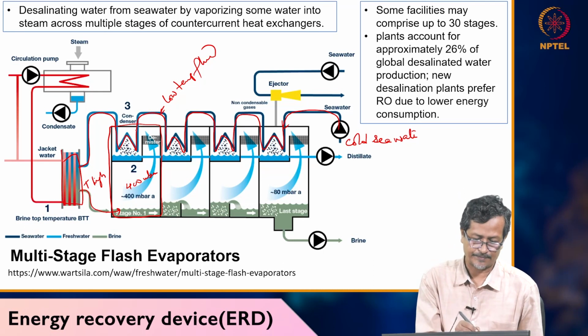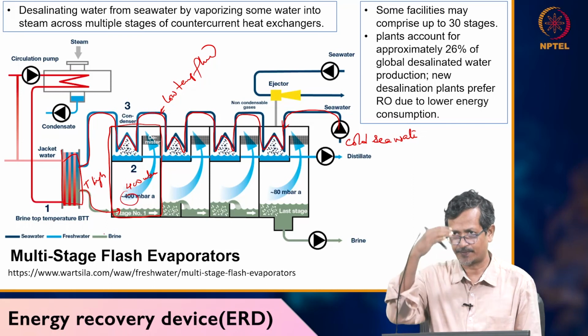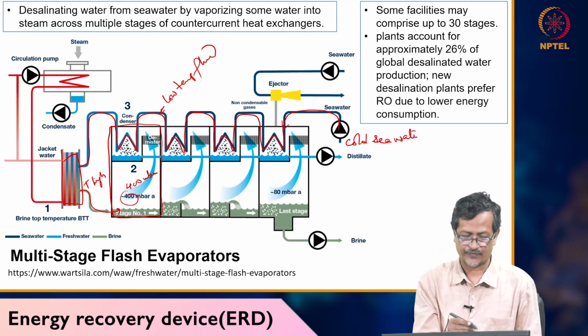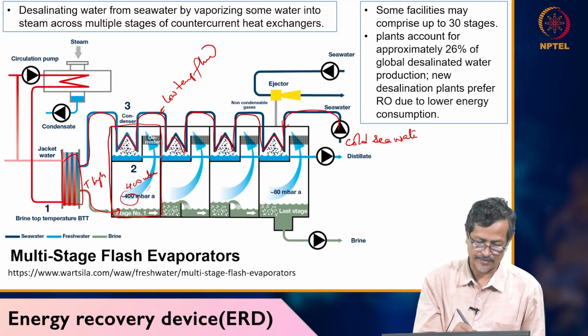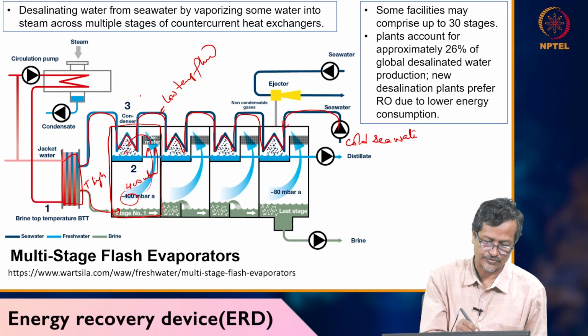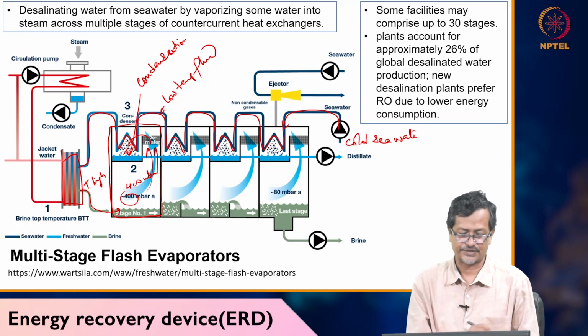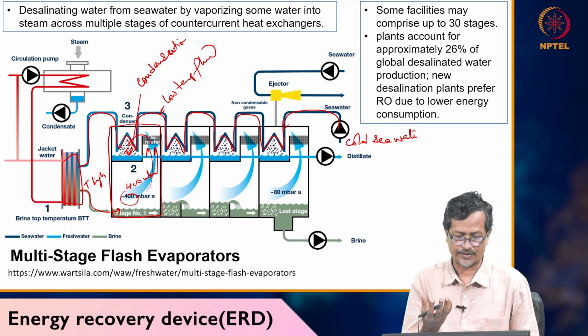Okay. Some fluid is coming to the first chamber after heating. Now, here pressure is lower, 400 millibar, and in the upper part some cooling pipe is also there. When it gives off lots of vapor, the vapor will get cooled down and collected here. Okay. So, here vapor is cooled, condensation. Okay, condensation is happening.